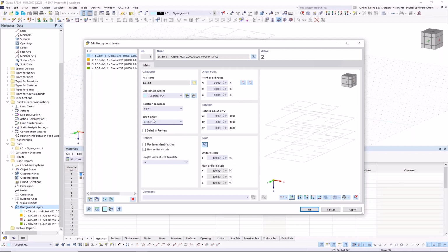But these are just predefined points defined by the outlines of your DXF file. And maybe in my case, I want to present here, you have a certain reference point you want to use. Maybe it's aligned to a frame you have, or maybe to your building grid. So that's why I will show you how to select your insert point in the preview.